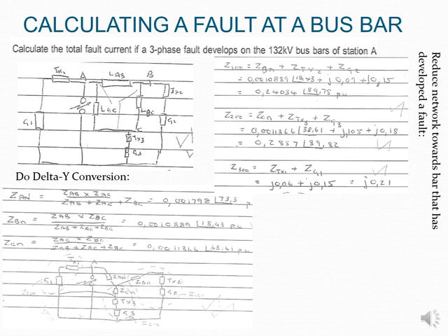You can see I've got a Z100, which consists of my furthest line at the bottom, where I had ZBN, XX2, and G2. Then I had my Z200, which was the bottom part where I had the transformer 3 information. Then I had my Z300, going towards bus 1, with generator 1 and transformer 1 in it.